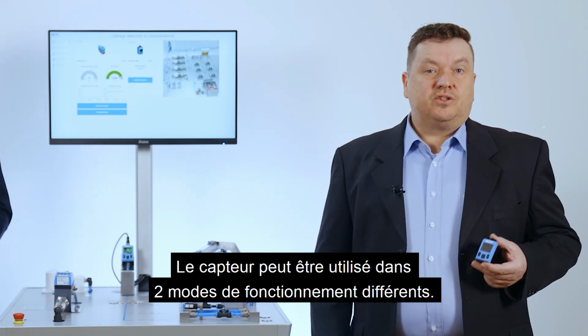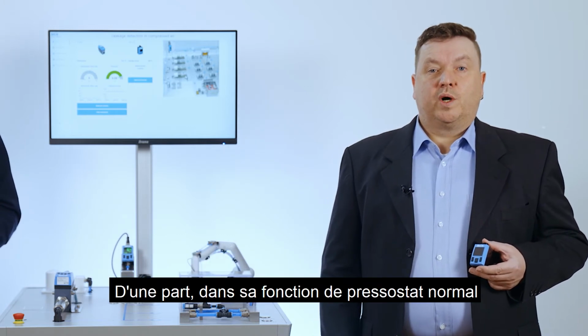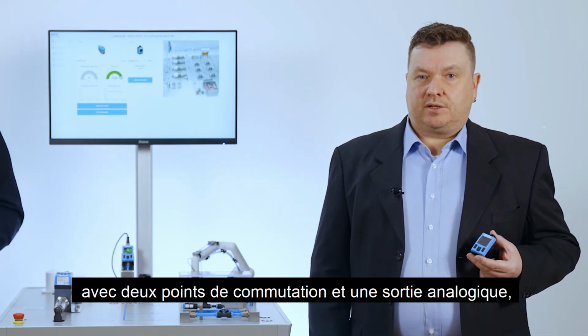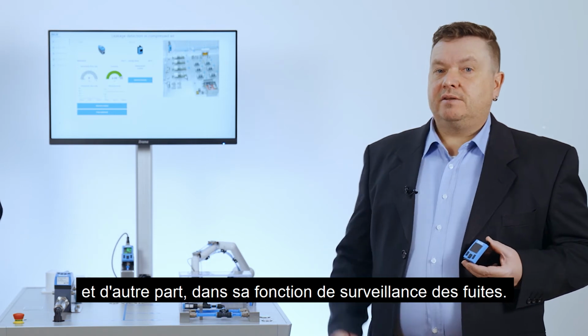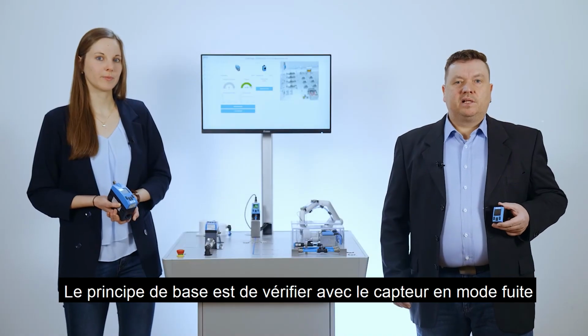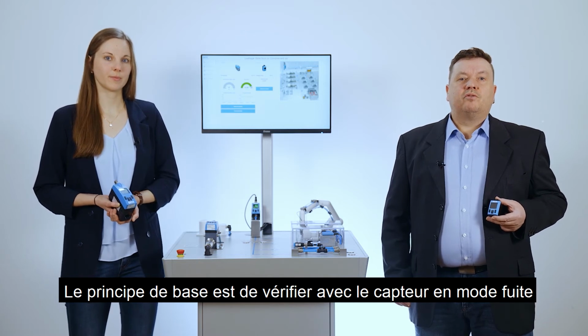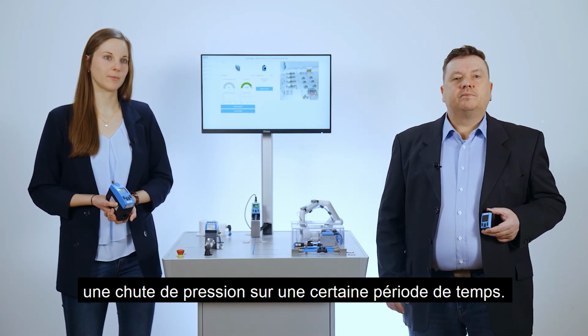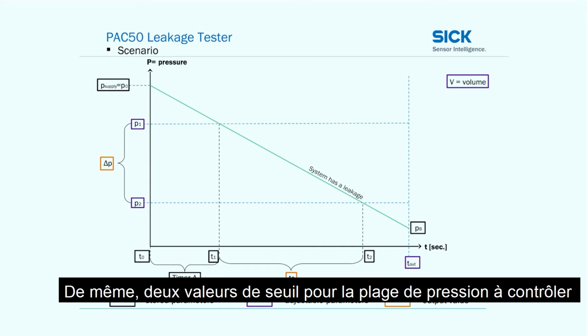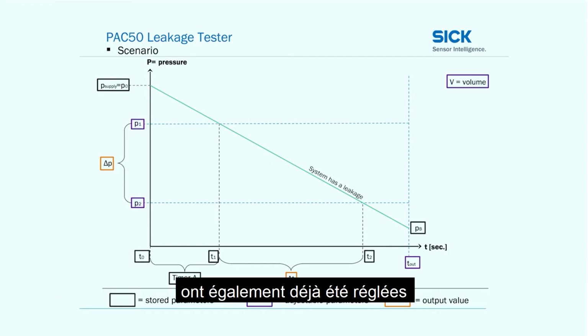The sensor can be used in 2 different operating modes. On the one hand, in its function as a normal pressure switch, with 2 switching points and analog output, and on the other hand, in its function as a leakage monitor. The latter case is to be demonstrated with the help of the exhibit. Basically, the built-in sensor checks a pressure drop over a certain period of time in the leakage mode. The duration of the measurement up to the time out was programmed into the sensor for this purpose. Likewise, 2 threshold values for the pressure range to be checked were already set in advance into the sensor.